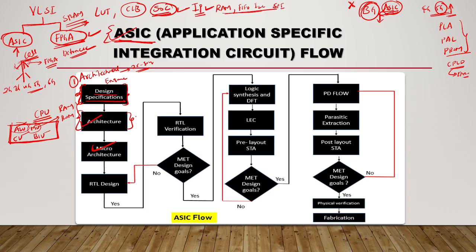First, architecture. That chip is used, suppose, if you want to design an SOC. In an SOC, what peripherals are required? You need to use an ARM processor. You need to use some peripherals like I2C, SPI, UART. All of those should be connected with AMBA protocols. That means they should be connected with AHB, AXI bus interface. So all those are done by the architecture or microarchitecture.